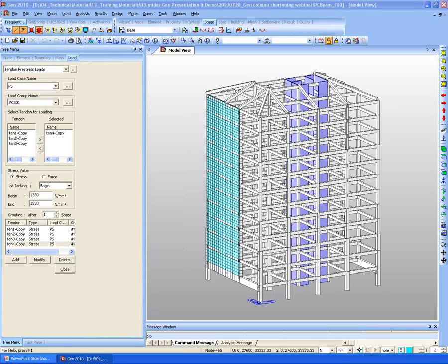For the lateral load, there is another question if we can enter the lateral forces during the construction stages. Yes, we can consider the lateral loads as well. By entering them as beam loads or nodal loads, we can activate or deactivate them during the stages. Only the live load or wind load or seismic load will be entered in the post stages.